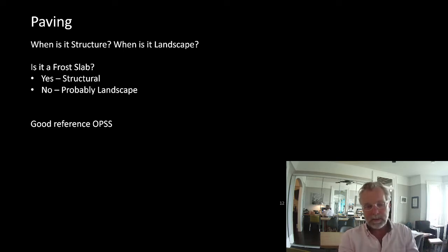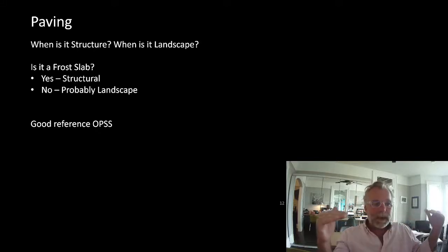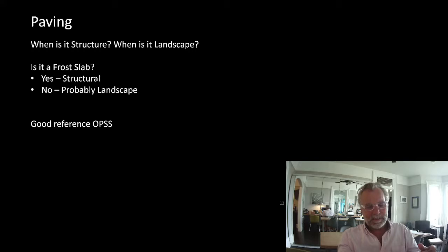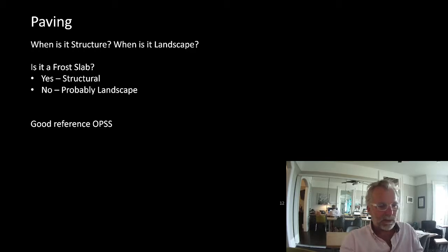Generally, in our area, it's considered to be 1.2 meters or 4 feet. So the walls are below the frost level, and the soil can heave and settle as it sees fit. Because there's an airspace underneath it, now that slab is spanning. That is the thing that makes it structural. It was structural anyway. That's the thing that makes it the structural engineer's scope of work.